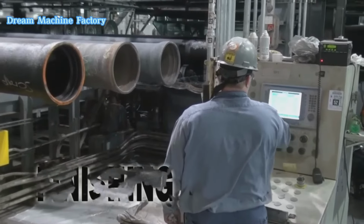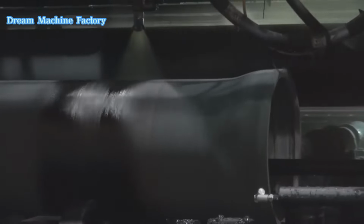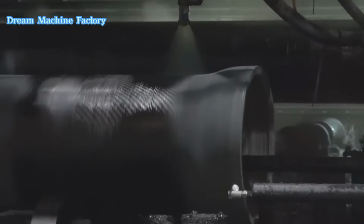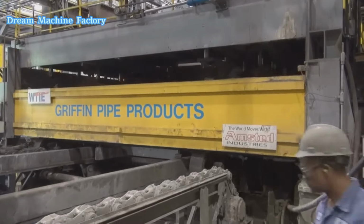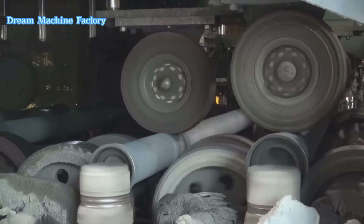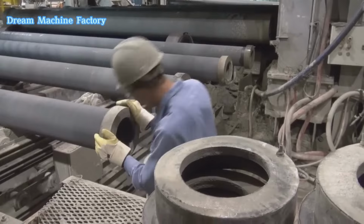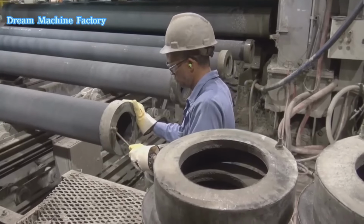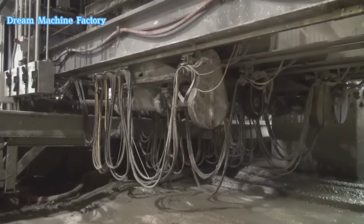The finishing process is essential for enhancing the durability and corrosion resistance of ductile iron pipes. After annealing and inspection, each pipe undergoes lining and coating procedures to protect it from both internal and external environmental factors. The first step in finishing is the cement mortar lining, which protects the interior of the pipe from corrosion and prevents the buildup of deposits that could reduce water flow.